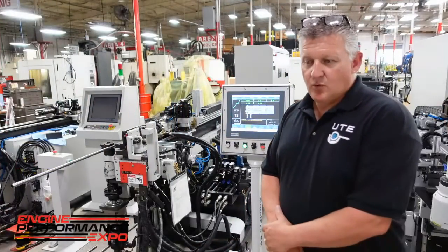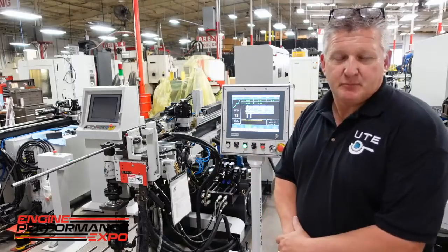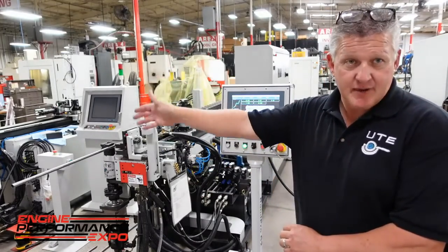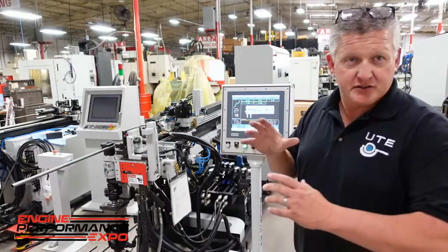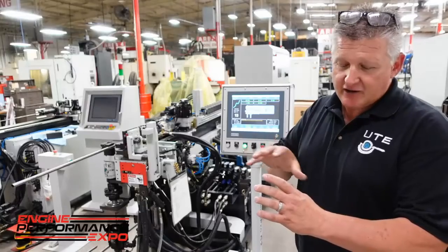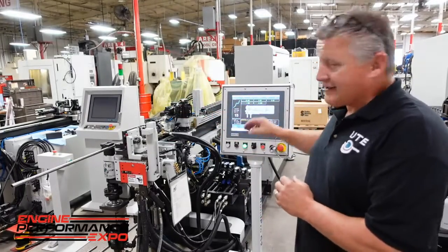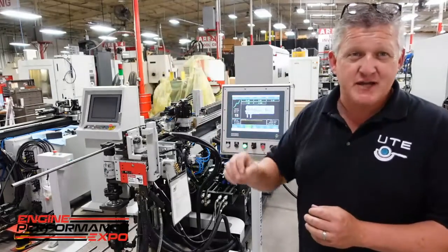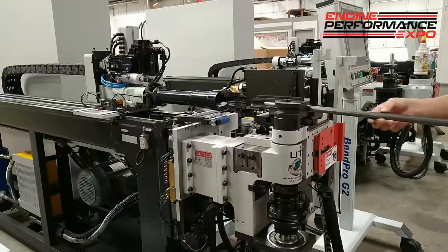Here we're going to bend up a tube shape that's been predetermined, and take it over to the measuring center and measure it. The computer in the measuring center is going to compare it to the print data. You're going to see that the out of tolerance parts come up in red. We're going to send those corrections back to the bender and bend the second one. Then we'll take the second one over, measure it, and you're going to see that all the tolerances come in green. That's a perfect part to the print.